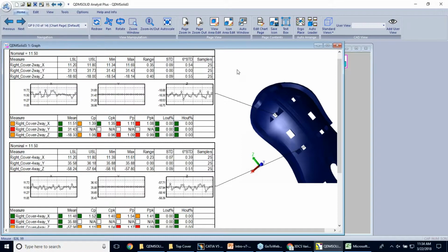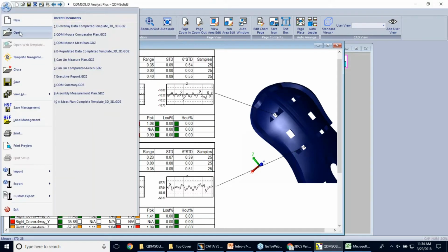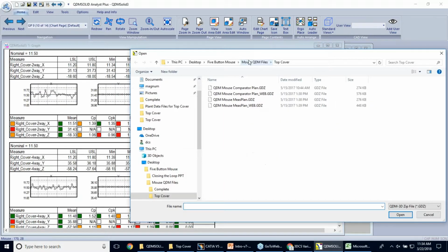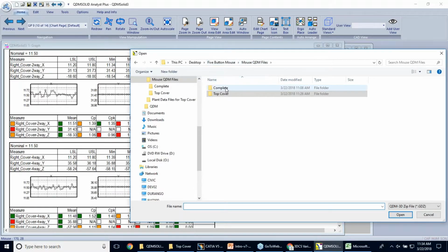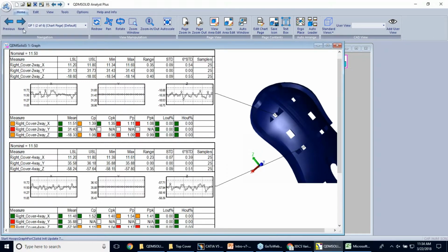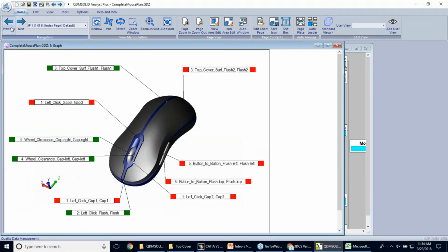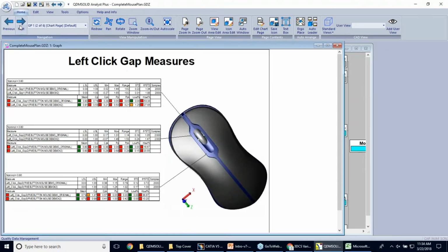As a follow-up to that, on the measurement plan, this is a little bit more in regards to datums: how you define the datums. This was a question from a customer that's related to what we're talking about right now. On the measurement plan, how we define datums from which measurements is a requirement. Different points may have different datums based on functional requirements. That's correct. In 3DCS, we would label those points.